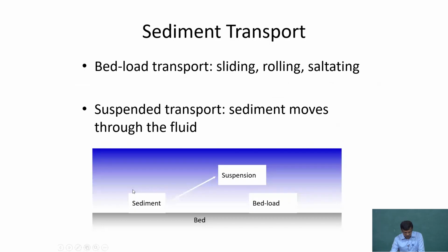There are two predominant ones, because in the modeling itself there are two different models, a bed transport model and a suspended transport model. The bed load transport process is different, and suspended load transport is just moving by advection, by the fluid particle velocity acting on the sediment.